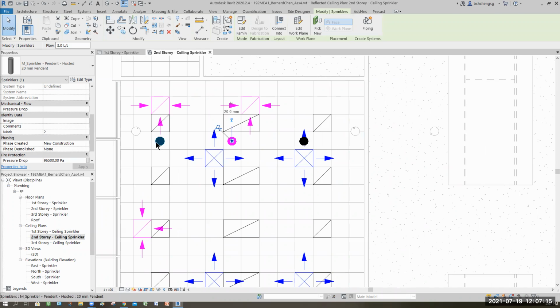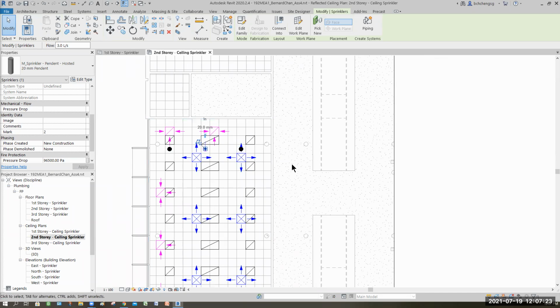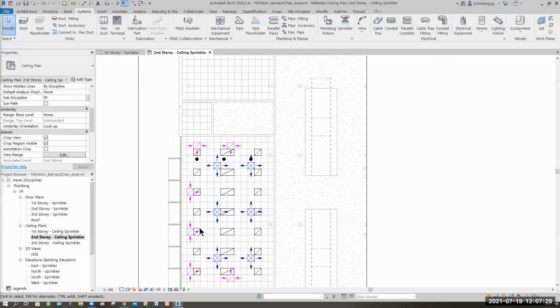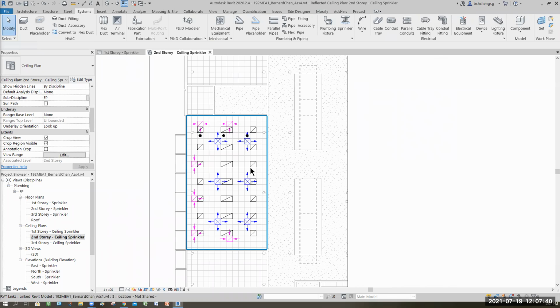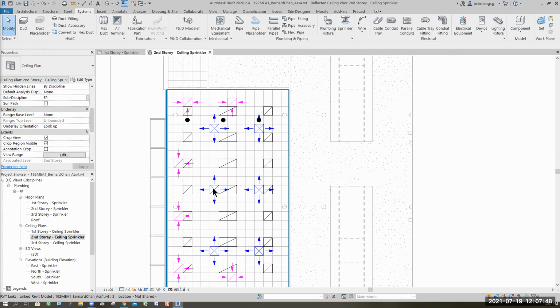So sometimes you decide, you may want to put it closer here. I do here because hopefully there's no clash on here. At least this is a clear space for us to insert. Now you see the reason why all this spacing is important. No clashes. That's why I do sprinklers last, because at least the position we can adjust, not like your lighting and your HVAC. They are more on fixed location, which is a lot more flexible.